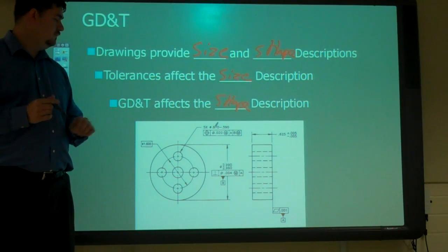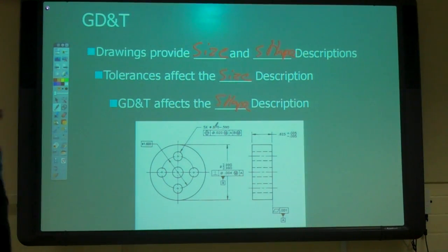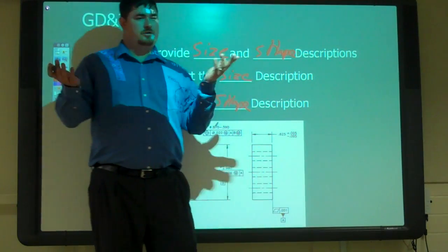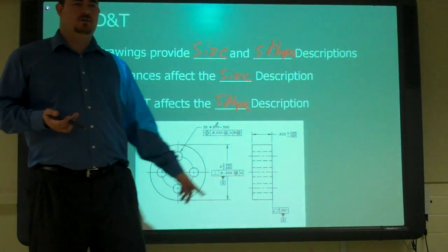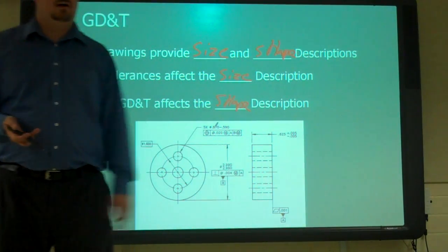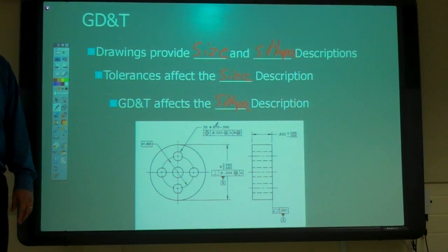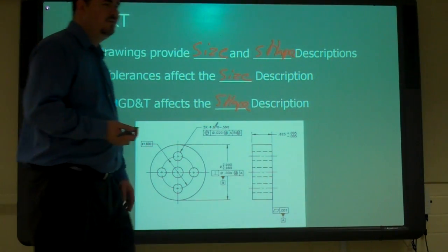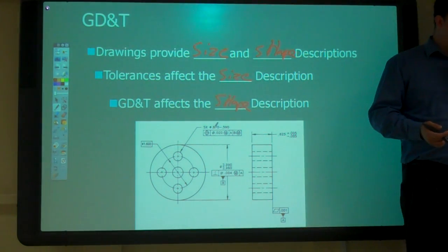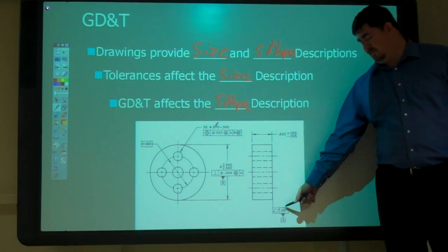Now, for example, on that piece, just giving it a flat symbol won't do. You have to actually give it a tolerance for it? Yeah. Because if you just say flat, what's your tolerance? Nothing's perfect. Nothing's going to be perfectly flat. Even glass isn't perfectly flat. Mirrors aren't flat. Polished things aren't flat. Water to vacuum is. That's not a manufactured thing that you're going to be able to live with. Nothing is flat. Nothing's perfect, so you have to have a tolerance on everything.